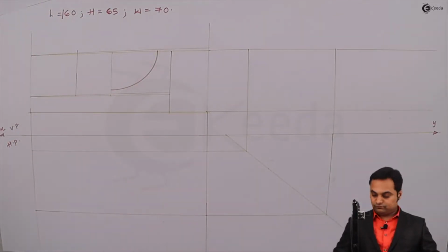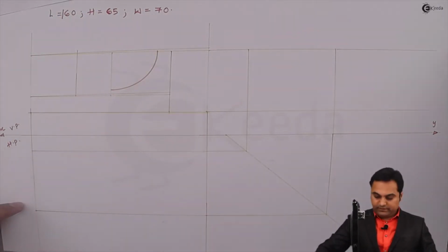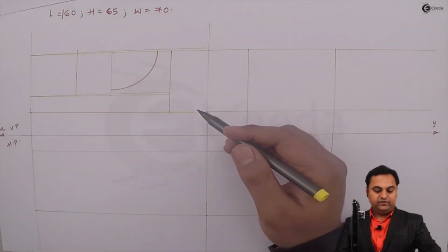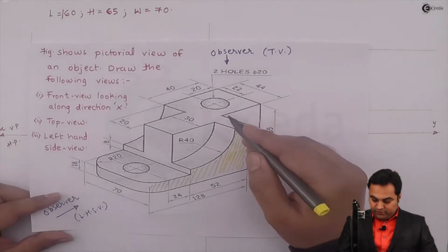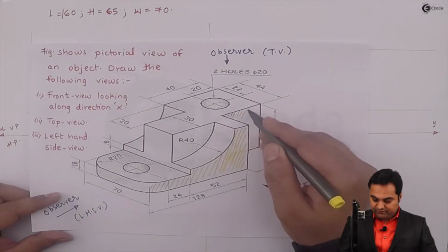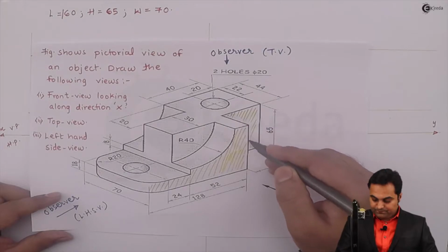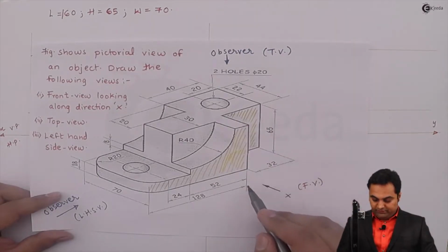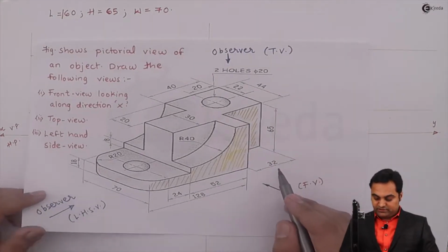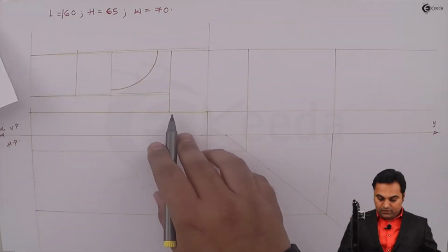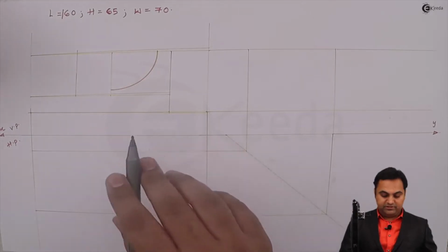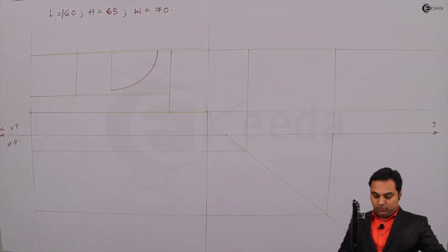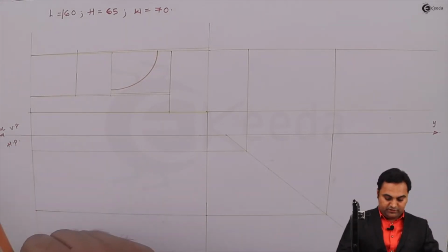After that, I have drawn this portion. Then here even this rectangle is there which will be seen from the front. So whatever remains out of this is the other rectangle. So 128 length I have taken, whatever remains is for the rectangle. Now I'll go on making it dark, starting with the arc.